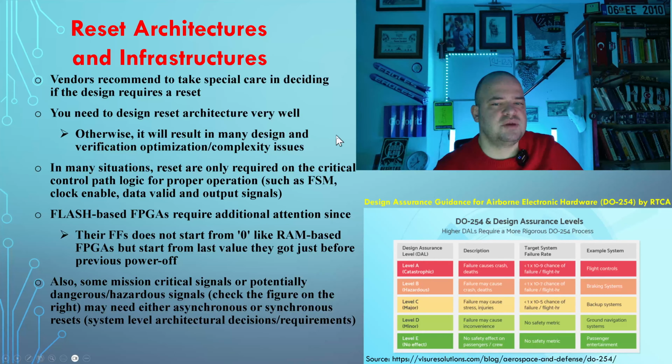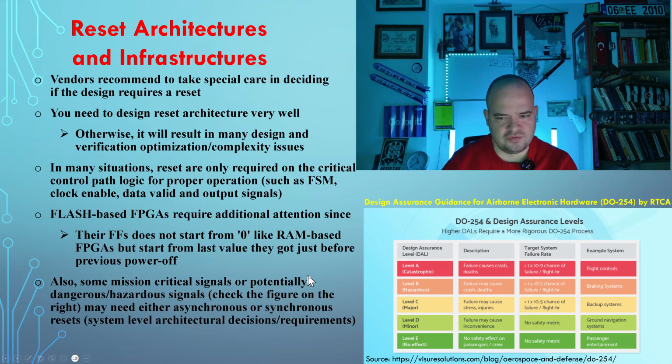Next bullet, flash-based FPGAs require additional attention since their flip-flops do not start from 0 like RAM-based FPGAs, but start from the last value they got just before the previous power off. Yes, this one is important, as the others I mentioned. Also some mission critical signals or potentially hazardous signals. Check the figure on the right. This is the design assurance guidance for airborne electronic hardware, DO-254 by the RTCA committee.